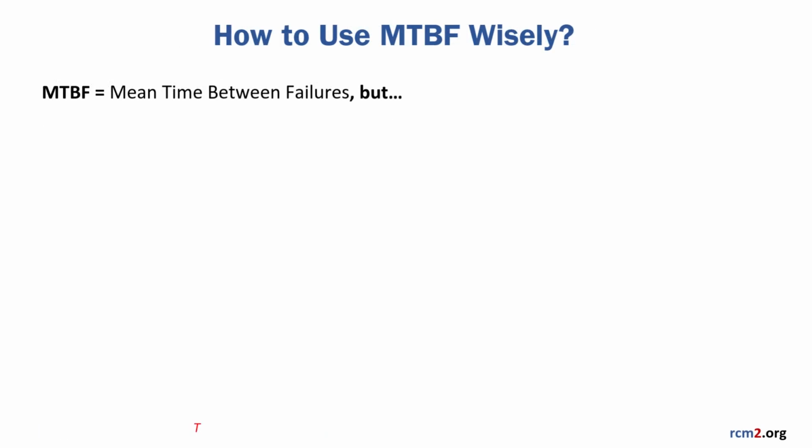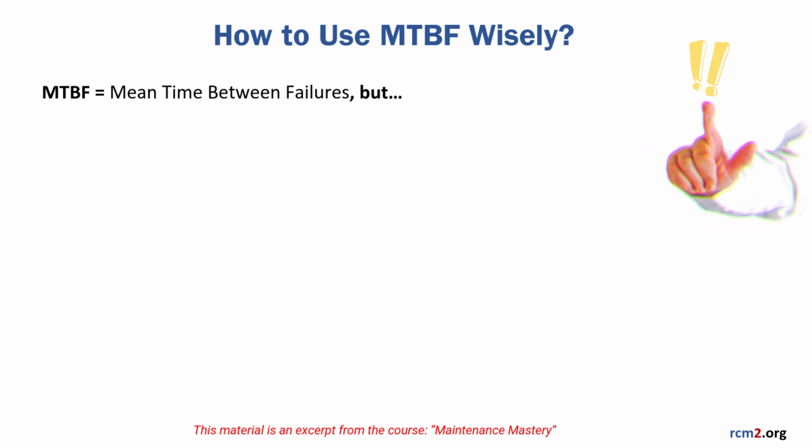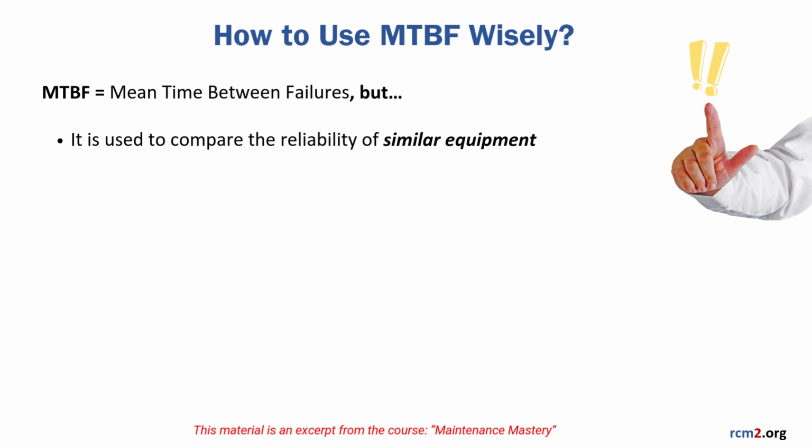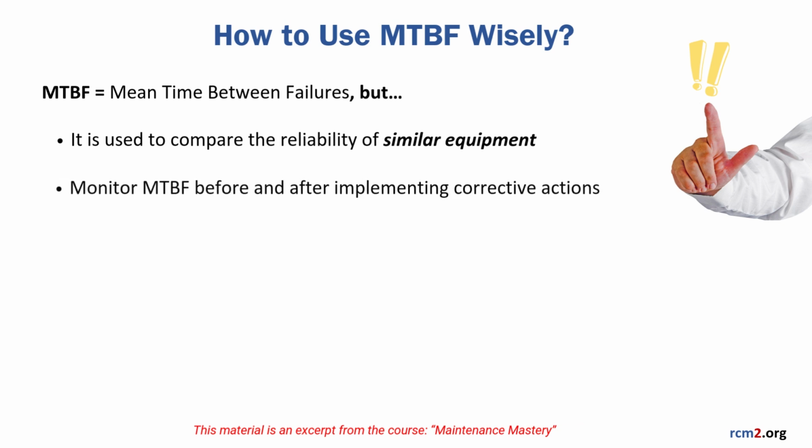How to use MTBF wisely. MTBF can be a useful metric, but only if we understand its limitations. It works well for comparing devices operating under similar conditions. It's also helpful when monitoring the effects of changes. For example, if MTBF increases after preventive actions have been implemented, that's a good sign.